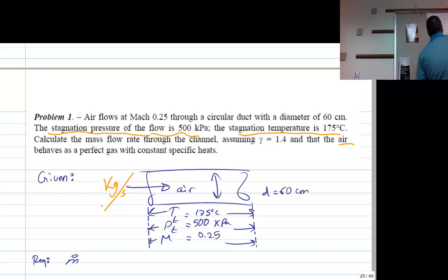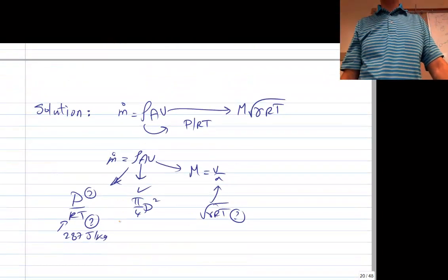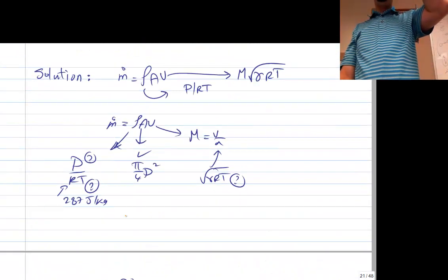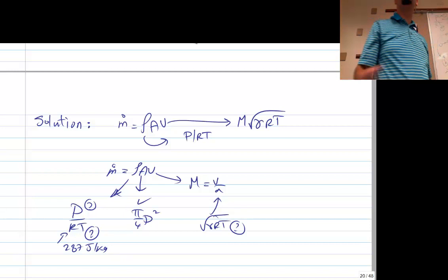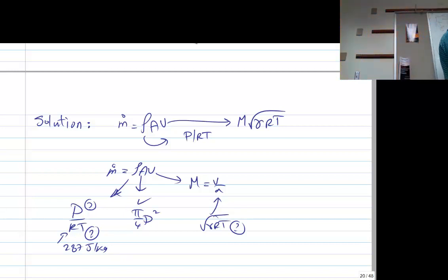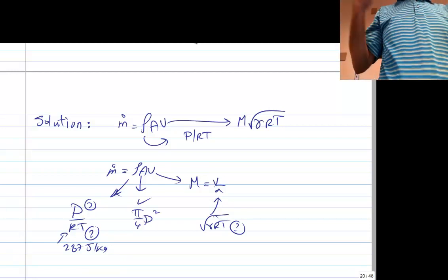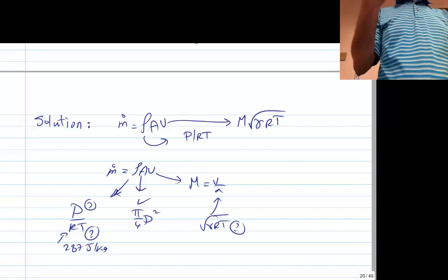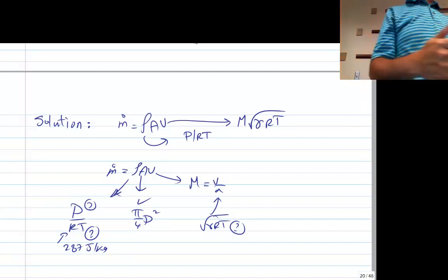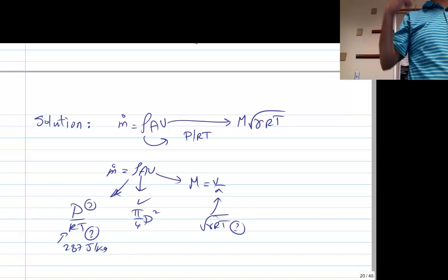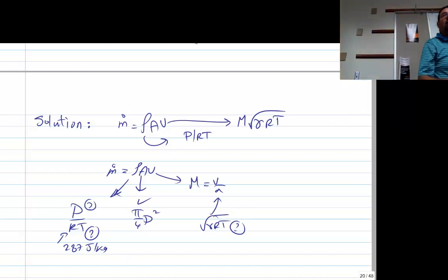And so back again to the equation for M dot. You can get M dot. I would like to stress again that when you try to solve those problems, you should solve it from the middle. What is the main equation? How am I going to get my M dot? It's rho A V. How am I going to get rho A V? Well, I have to get the density, and then the velocity. Then how am I going to get my pressure and temperature? Well, I need those conversions. Once you have laid out the plan, you can start writing the solution from here.